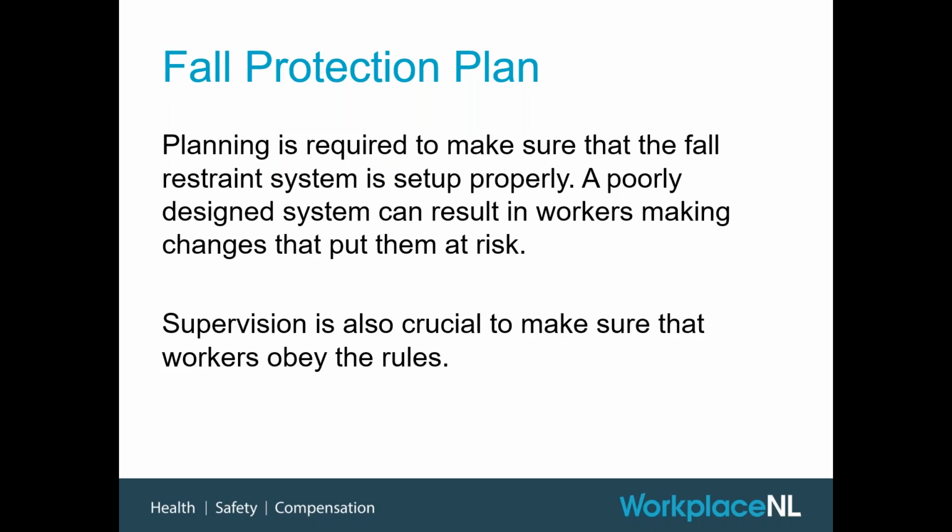So for example, if you put someone in an SRL, like I mentioned earlier, and they have the potential to go further than, say, the 4 feet that was allowed in the plan, it's possible that they may be tempted to do that. Often as well with restraint systems, supervision is really important to make sure that workers are following rules and guidelines that are in place within this plan. So just something to think about.